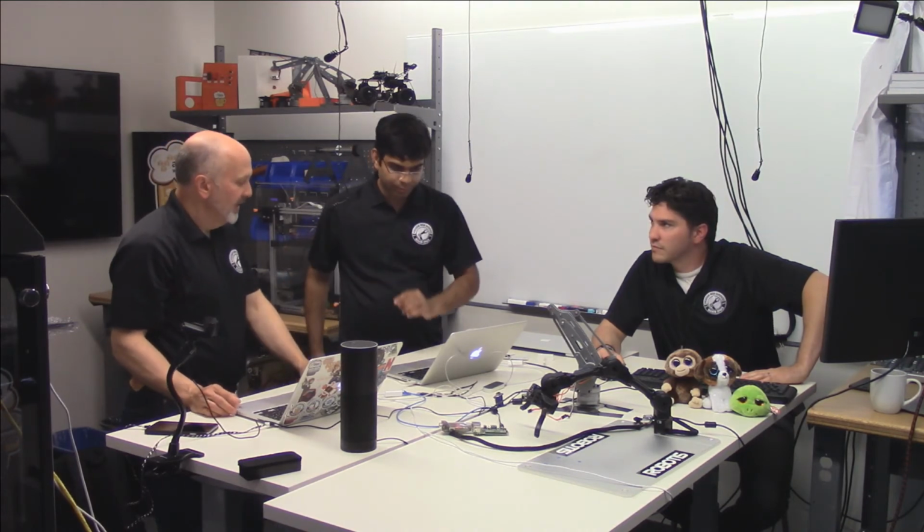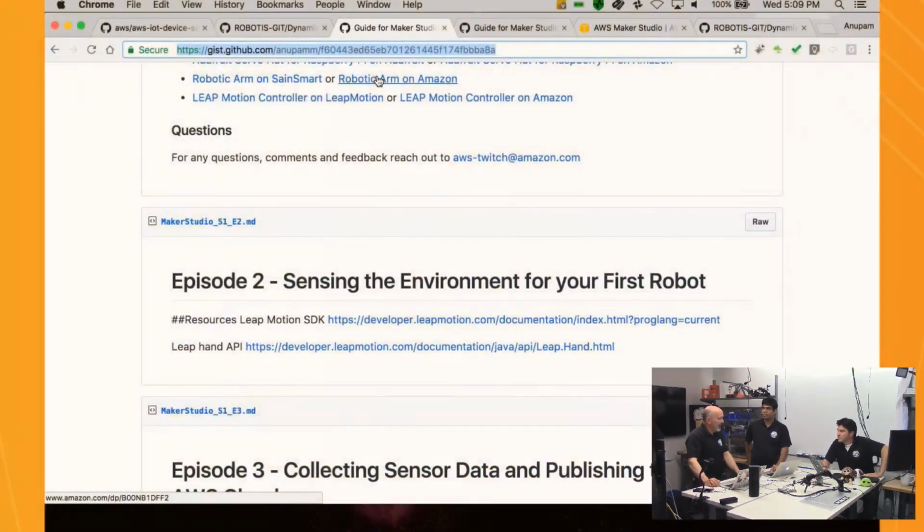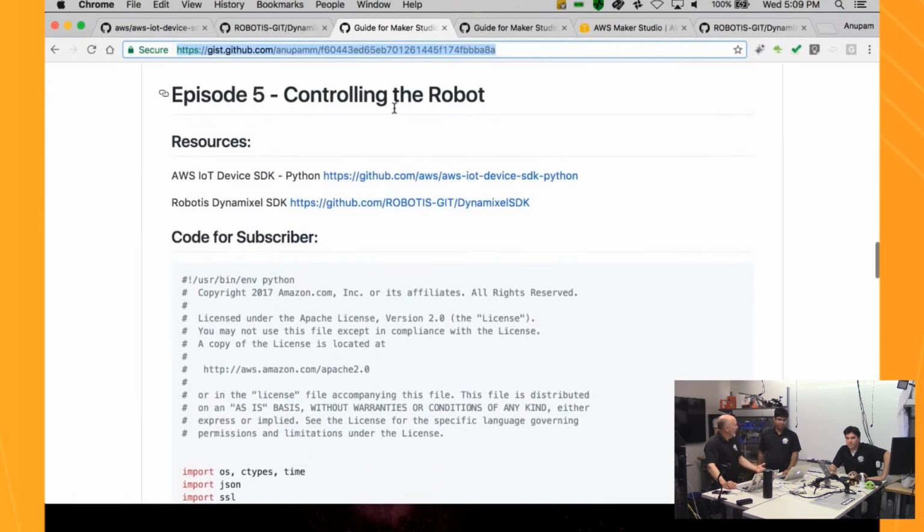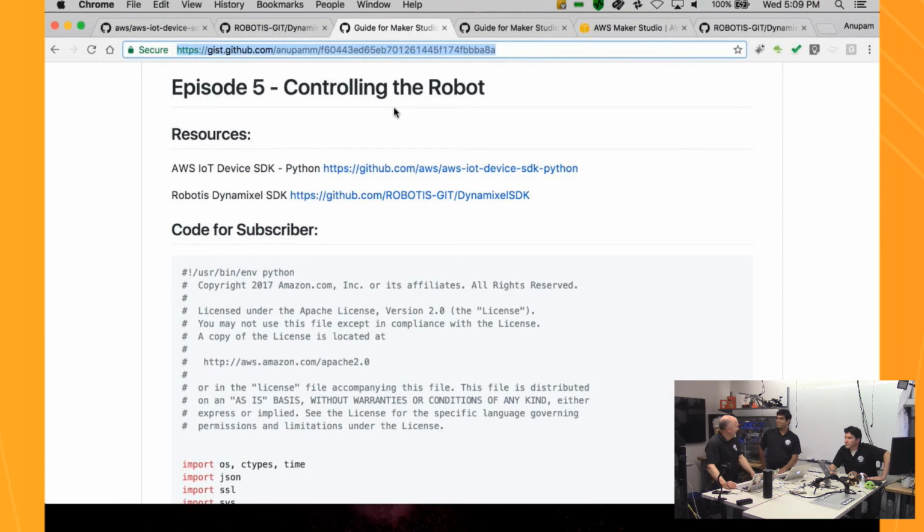Right, and so the benefit here is that when doing robotics, being a mere mortal, I can program in Python rather than getting down into C. And so what it means is that doing complex robotic applications is accessible to many, many more people. So we have this smart servo with bidirectional communication that has a lot of built-in functions, but we can access it from Python, Node, Java, what have you.